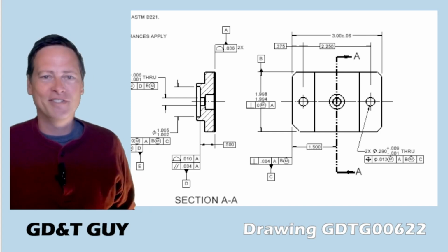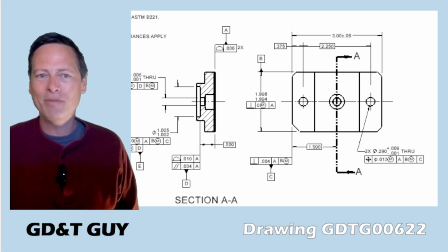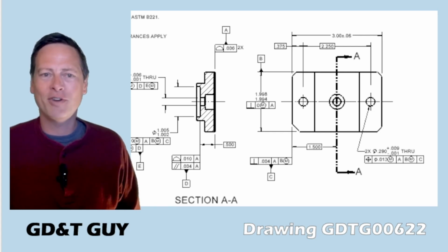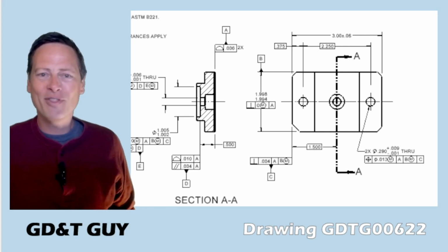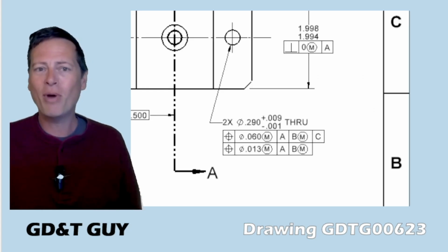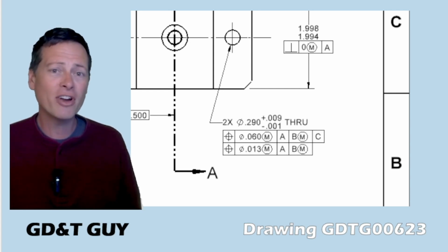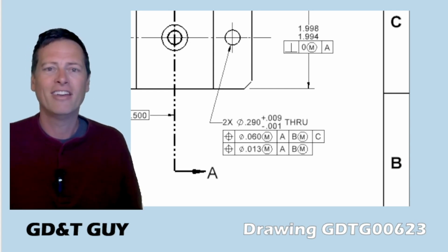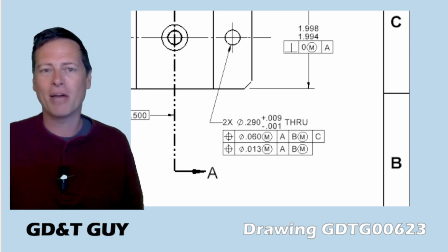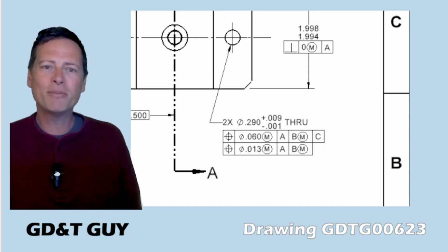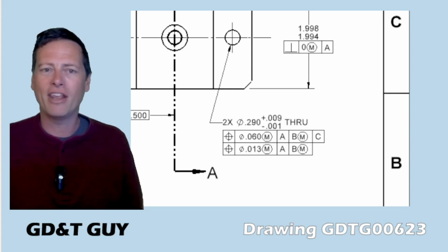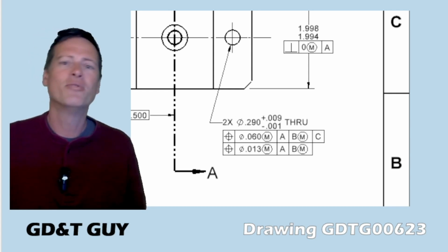But this is all crazy talk because of course we can dig a little deeper into GD&T and datum references to come up with a better requirement. We've only tried this one thing so far. Maybe a better way to view the problem is that the 13 thousandths diameter tolerance is good for locating the screw holes to each other and to datum B and the 1-inch diameter feature simultaneously, but there needs to be a looser tolerance locating all of that to the datum C leftmost end.